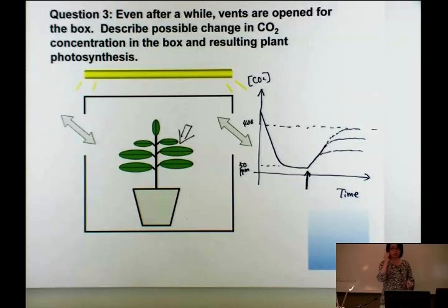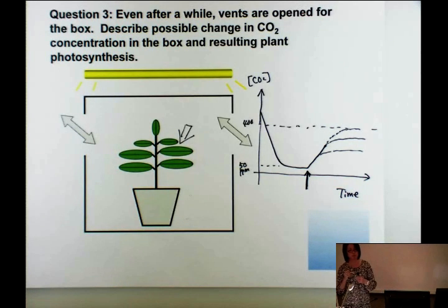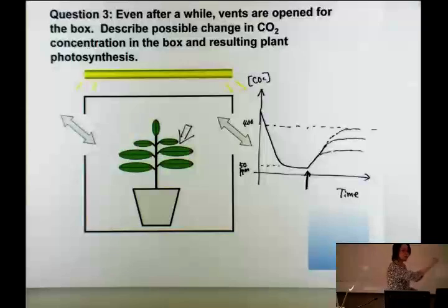If ventilation was really small, though, wouldn't it oscillate, like Caitlin said? If ventilation was really low, it would go up to 400, and then the plant would start photosynthesizing. Yeah, initially, if you are changing things very rapidly, you have this kind of oscillation, but it stabilizes anyway, because plants' photosynthesis balances with the supply of CO2 coming by ventilation.